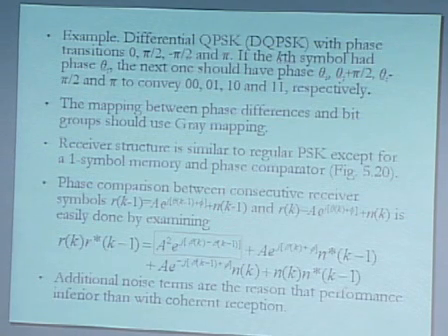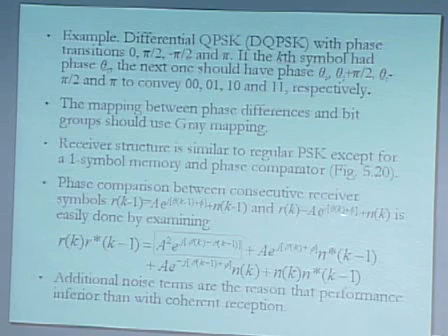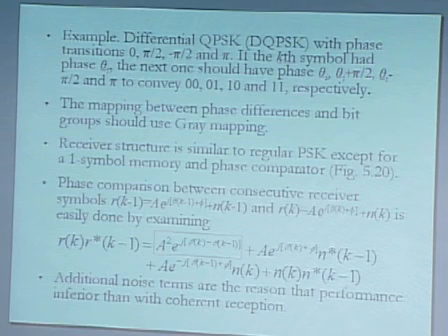And then in the next symbol time, in the next tick of the clock, we get r of k equal to the same amplitude, but a different phase, theta of k, the same oscillator phase, this one is constant, plus a different noise.